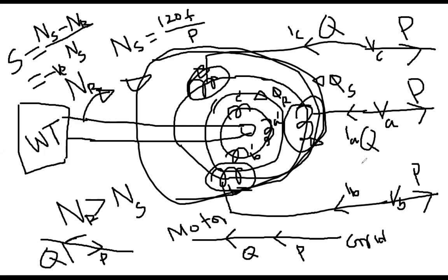Now everybody see, what is the problem with that Q? As you understand, Q reactive power is needed to produce the required magnetization. Otherwise the system will not work, whether it is motor or generator. So what will be the consequence of drawing the Q always? Low power factor. Very good. There will be low power factor, so therefore the voltage might be low at the terminal.